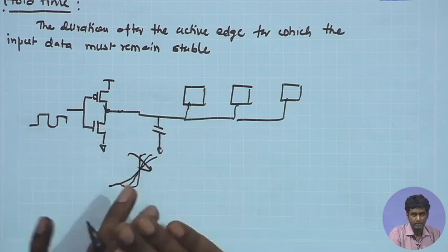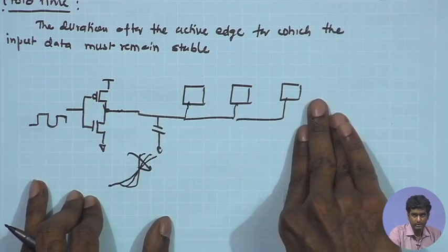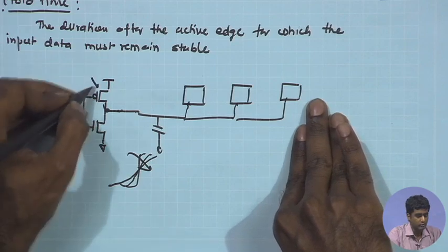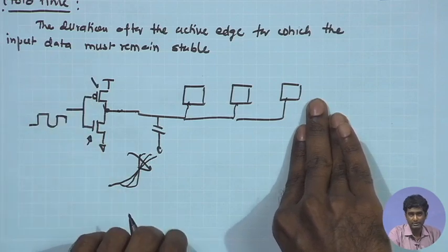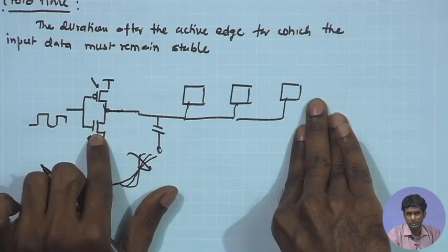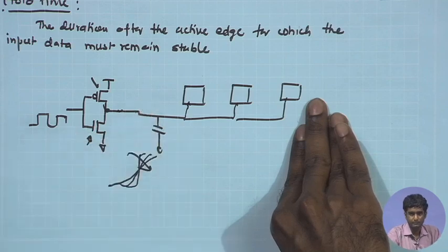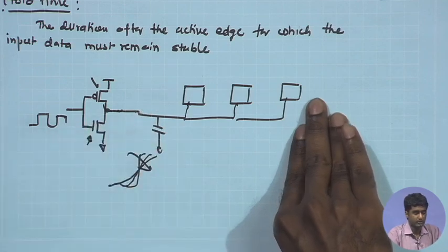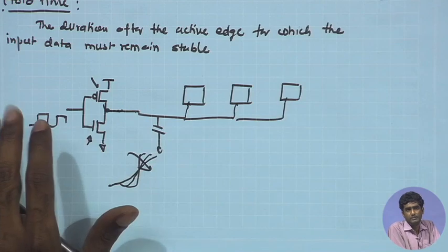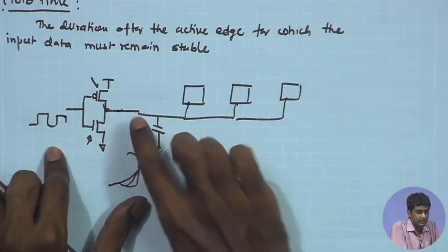Therefore, this condition should be avoided. In case a single gate is supposed to drive a large number of other digital blocks, you can try to make the size of the NMOS and PMOS larger, so that correspondingly the current pumped in by this PMOS and NMOS also becomes larger, and as a result the rise time and fall time is maintained. So, this is something to be careful about whenever you are using inverters or logic gates to drive the next stages, especially in case of clock.